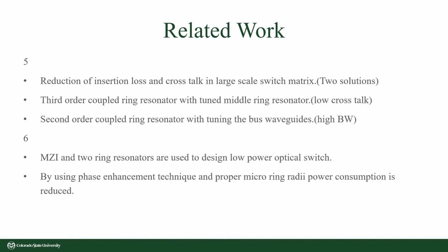To build a large-scale switch matrix, optical switch elements with low insertion loss, low crosstalk, and low power consumption are highly required. There are two possible solutions for this. The first one is using a third-order coupled ring resonator with tuned middle ring resonator, and the second one is using a second-order coupled ring resonator with tuning applied to bus waveguides.